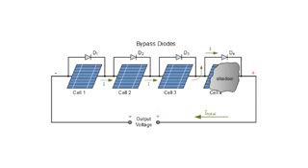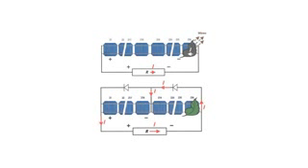A bypass diode is a cheaper but a less efficient solution for the shading problem. Please note that it is not always possible to place panels on the field. Obstacles are always around that can include buildings, trees, electricity or communication poles, etc.